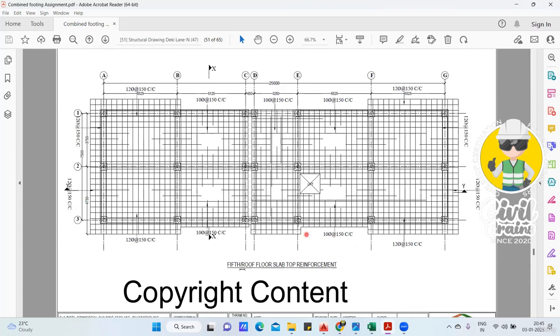So one thing I'll tell you. When you come to the roof floor, this is your roof floor, so the staircase portion slab will come. Why? Because it is the roof, no? You will have that mumty level. That is why here the slab will come in the final. So here this additional reinforcement of the slab you also have to consider.